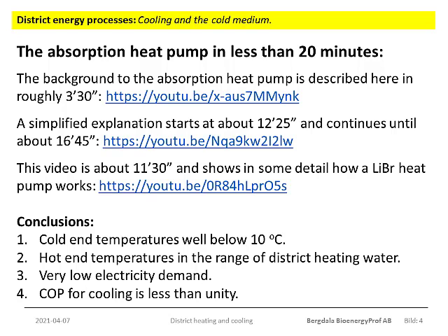So if you want to cool away 1 megajoule of surplus heat from a customer, you will have to input maybe 1.5 megajoules of district heat into the heat pump. And then you have to vent away 2.5 megajoules of energy from the plant. So it becomes a question of low-cost production of the district heat, and then of how much your customers are willing to pay for their comfort cooling.